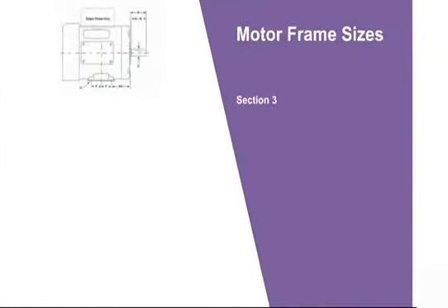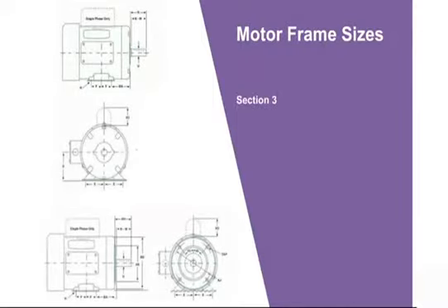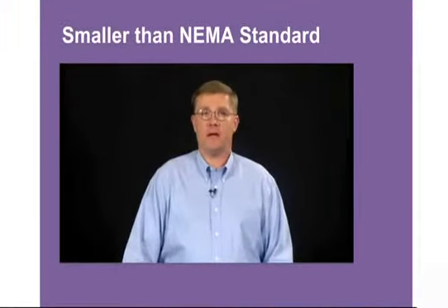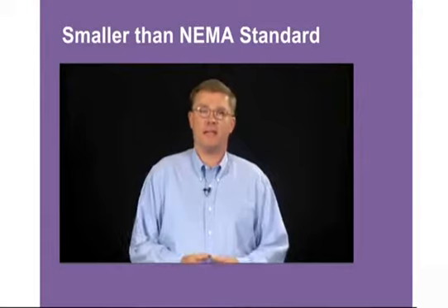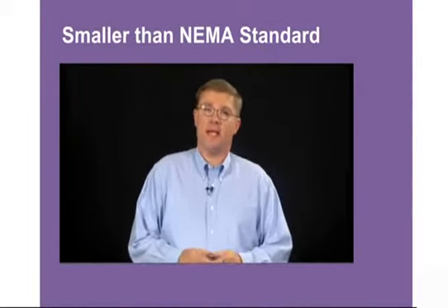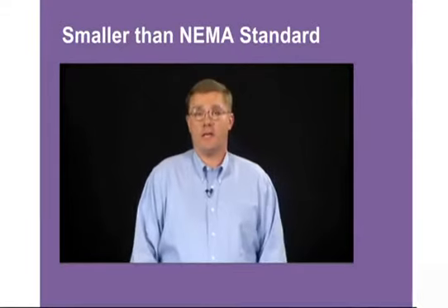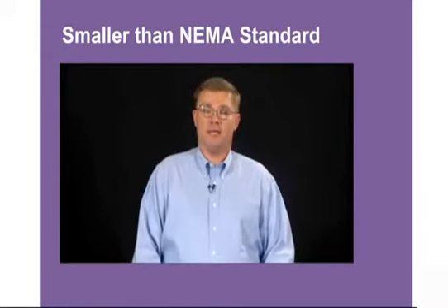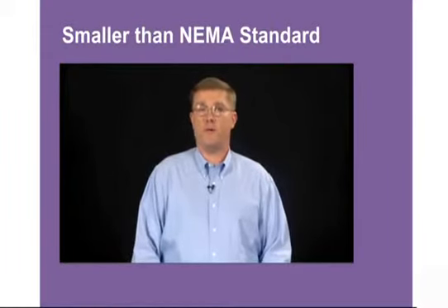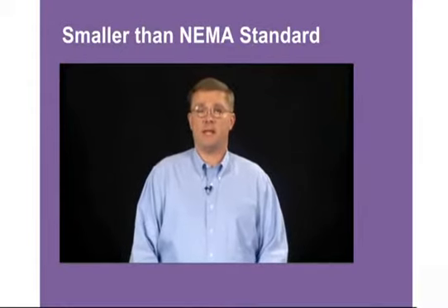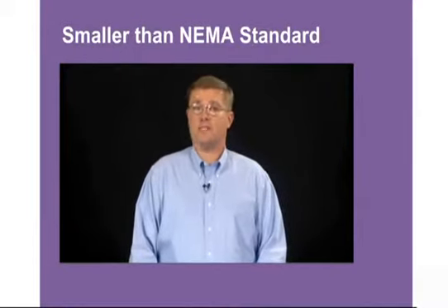This section discusses the relationship between a motor's frame size and the diameter of the motor. The next characteristic we talk about are frame sizes. And I get asked a lot, what does frame size mean? Well, frame size is also set by NEMA. There are non-NEMA motors, which are motors that are smaller than 42 frame. NEMA does not start until a 42 frame motor or a motor that is 5 inches in diameter. There are a lot of HVACR applications where the motor is smaller than NEMA standard.